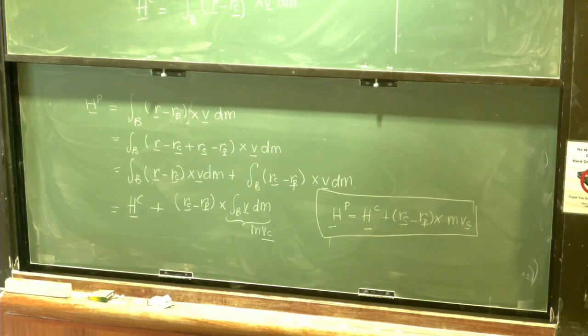Questions? Okay. So what I'm going to do is say that V is the velocity of some material point on the rigid body. So I can say that V minus VC is omega, the angular velocity of the rigid body, crossed with R minus RC, right? So R is the position vector of the point which has velocity V, RC is the position vector of the center of mass.